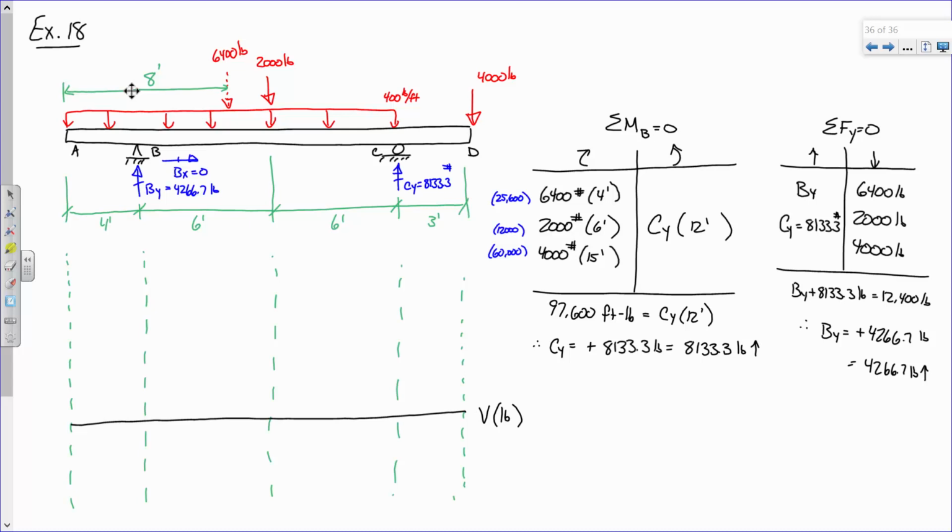Okay. Whenever you draw a shear diagram or a moment diagram, it's got to start at 0 and it's got to end at 0. Now, watch how this works. We start at 0 over here on the left, and when you're drawing this out, if you've got different colored pencils, that's great. Most engineering students don't. So what I do is I like to put little dash marks or arrows on this line because it helps me keep my eye focused on what's 0 and what's not. Sound good?